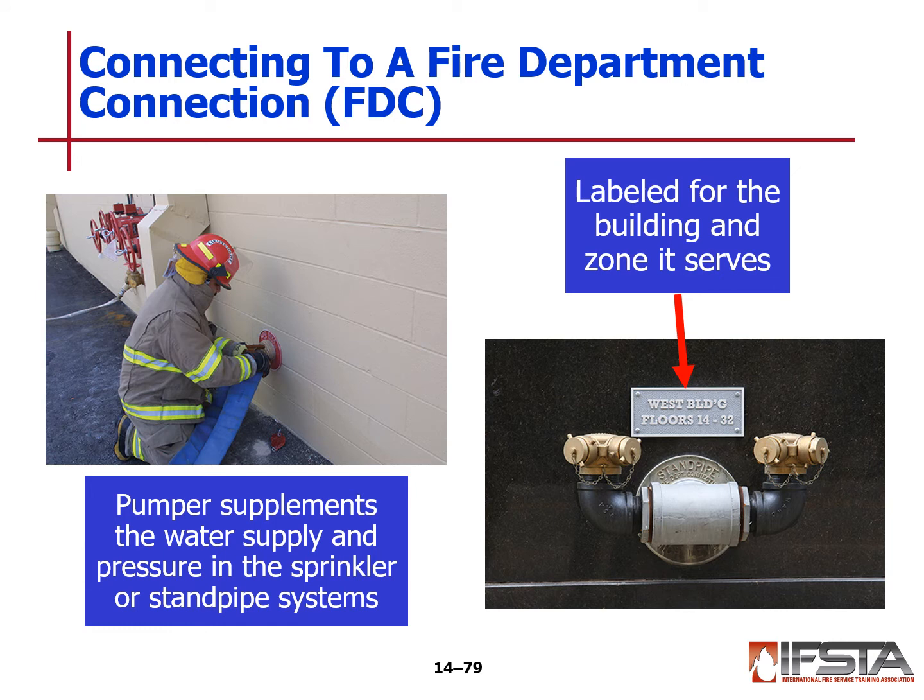When connecting to our FDC, or fire department connection, our pumpers will supplement the water supply and pressure to the sprinkler or standpipe system inlet. These should be labeled for the building and the zone that it services, and it should have a setup where it's easily connected. It should have caps on, protecting what's inside there, and certainly when we uncap them to hook up, look and check for debris.